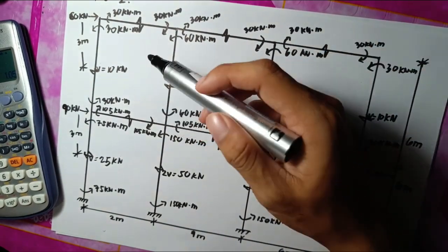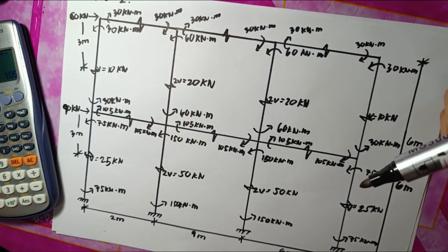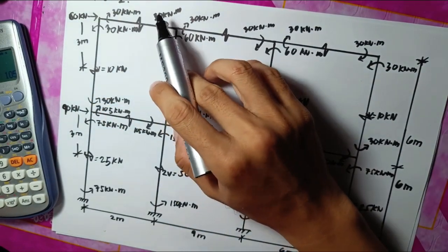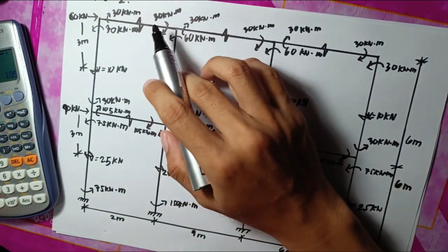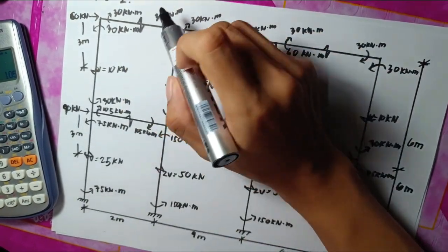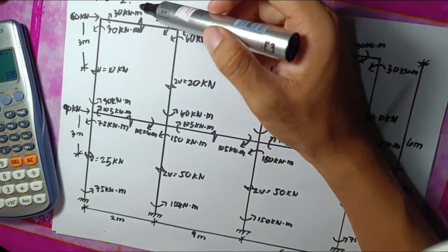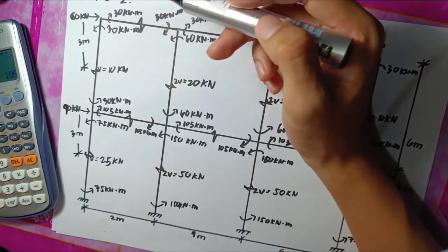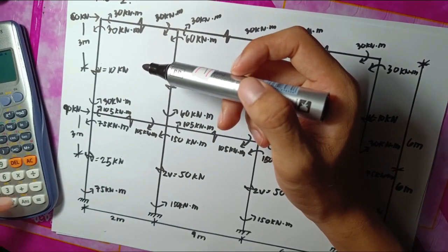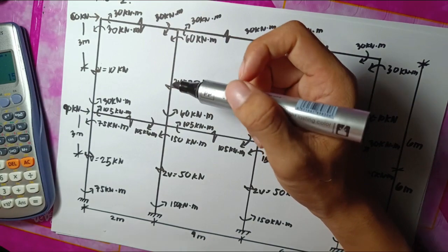So in order to get that value in the fourth step, girder shear, we must add the value of the horizontal column girder moment, or the moment of the beam. So 30 plus 30, 60, divided by 4, 15.